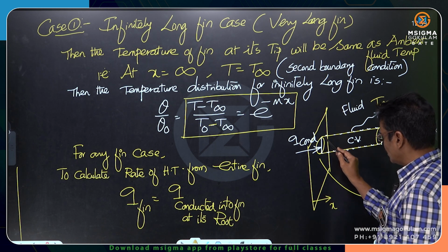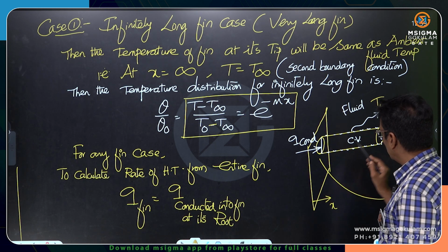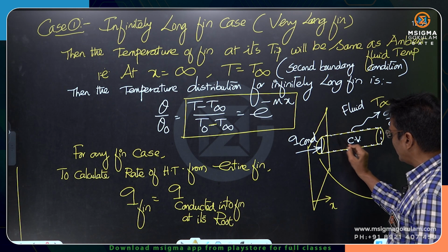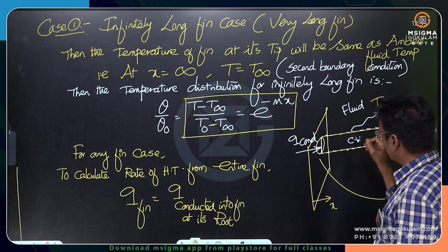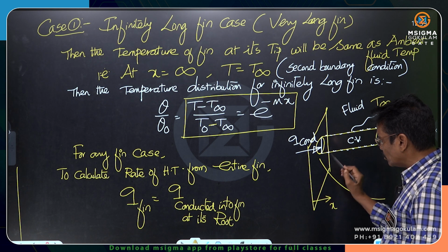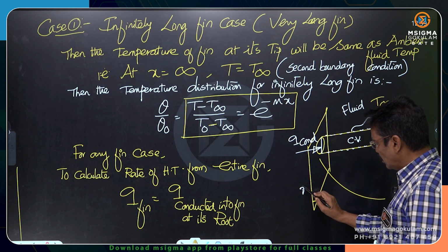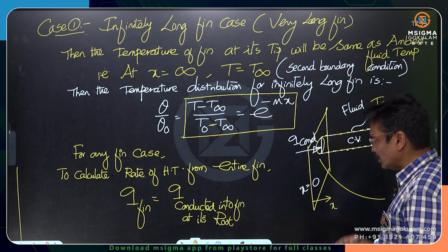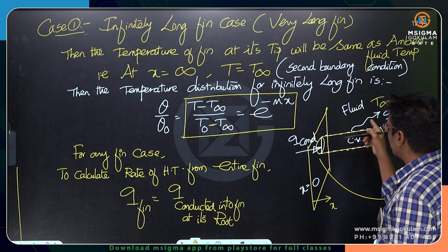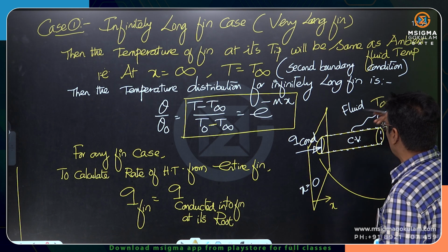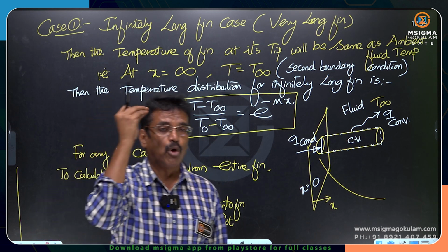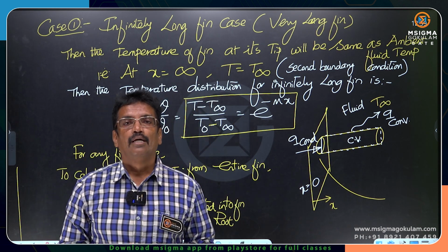That is, the heat conducted into the fin at its root, at x equal to 0, should be equal to the total heat convected from the entire surface of the fin to the fluid. That rule is valid for any case of the fin. Please keep this very important point in mind.